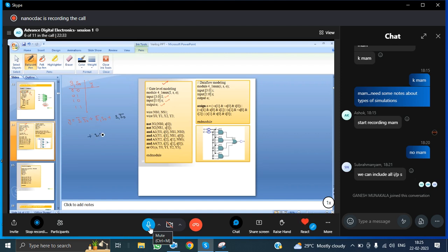I have to give the inputs also, one minute. Here the inputs I0, I1, I2 and I3 have to be given with these terms. So this is the equation for the multiplexer, the logic equation. If I implement this circuit, how many gates do I need? Look at how many plus signs I have.